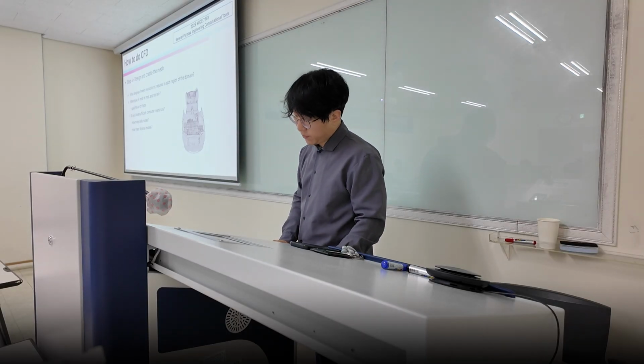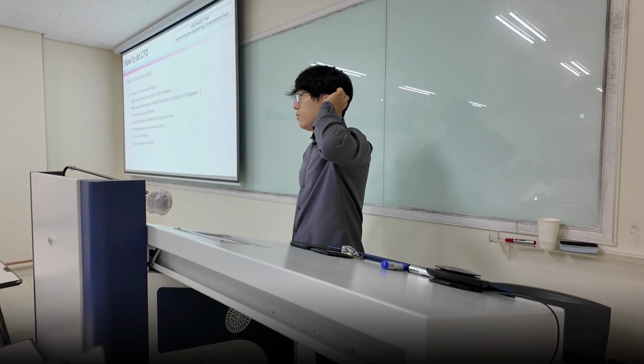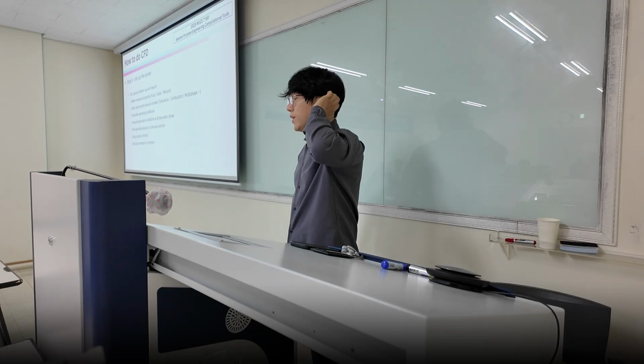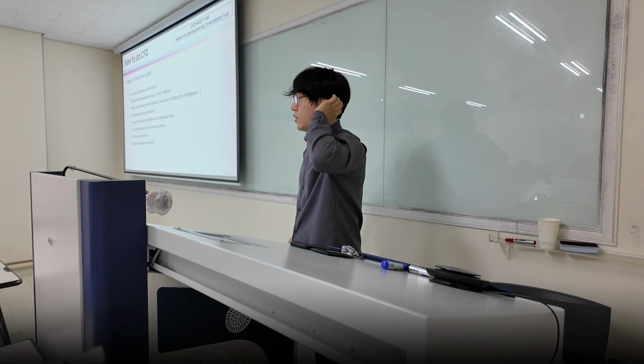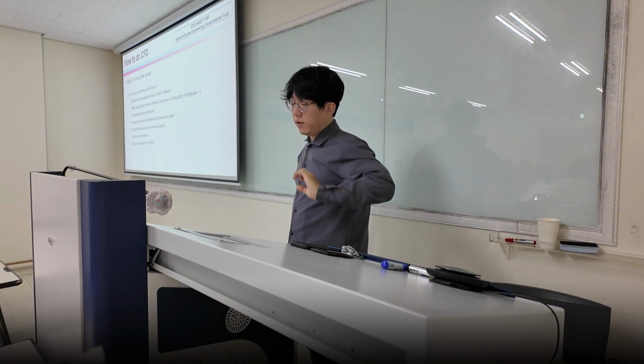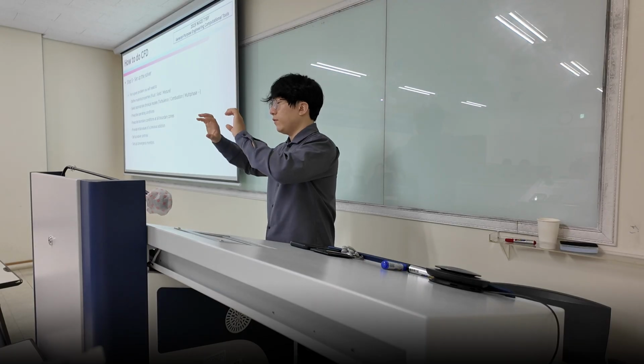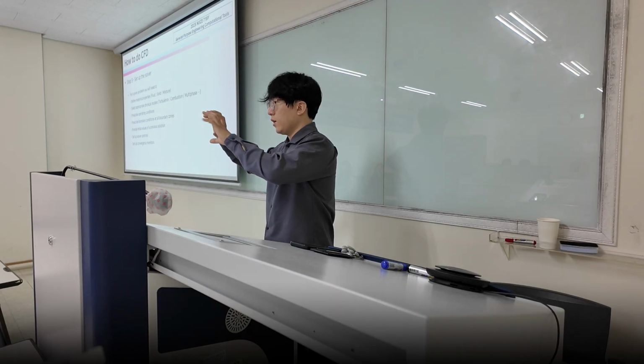Yes, from my experience. And then you're gonna set up the solver. Depending on the phenomena you want to analyze, you're gonna set up different solvers. One of the solvers we use here is the Eulerian solver, but you can also use Eulerian Lagrangian solver. But also those solvers can be attached to different types of modules.